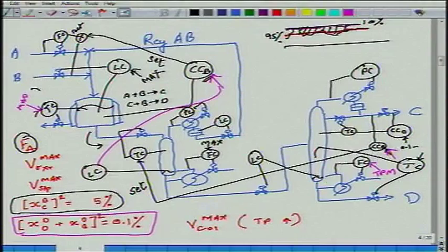Then it may so happen that before the effect from the reactor could trickle down to the bottom of that column, the column bottom level has either hit 0% or whatever, 20% or 80%, the max and low limit. That can make this level controller fragile. That's what I was saying earlier, we have to make sure.